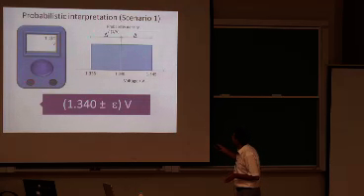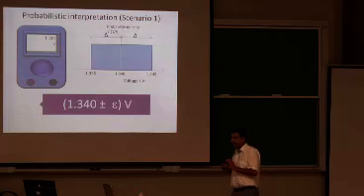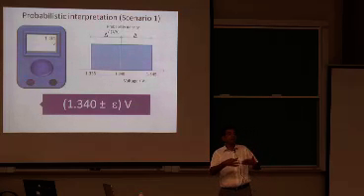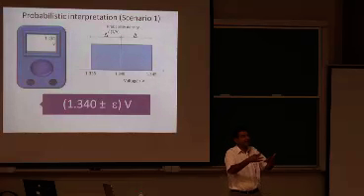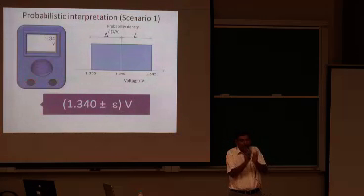So this range has an interval length of 2 delta, and a half interval length of delta. So what you could say is that associated with this reading on a digital scale, since the instrument has a finite resolution, it has a least count, a minimum gradation, you cannot measure better than that minimum gradation.